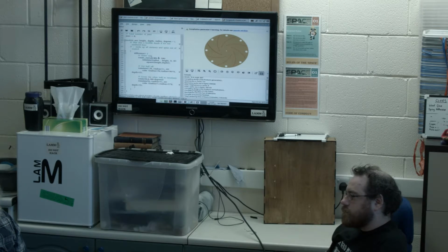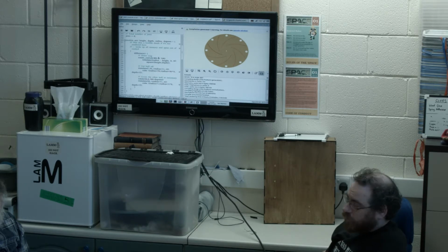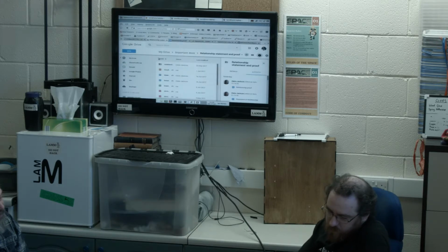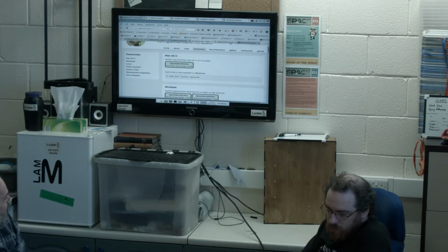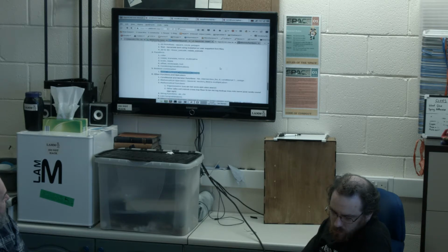Not radians. I don't think so. Actually, is it angle? I'm not sure, you'd have to look it up. It might do both. What I usually do is put FN at 200 and it gives me really nice circles when I export to the STL.